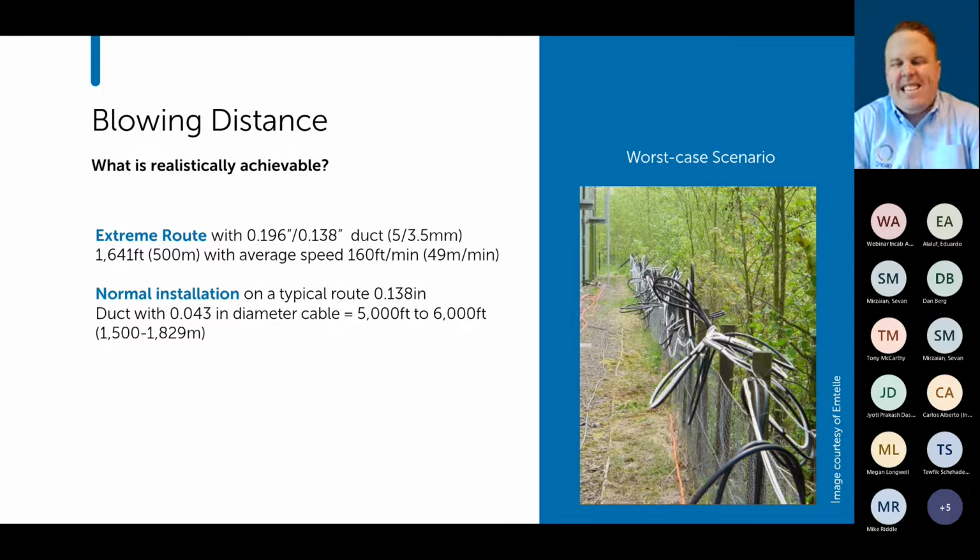We can see 5,000 to 6,000 feet out of a single run, which is, again, right, when we talk about a cost standpoint, if you can go 6,000 feet on a single run versus 1,500 to 3,000 when compared to a standard cable pulled through a duct, and your network calls for runs that long, all you're doing is decreasing the number of times that you have to install a handhole, a junction box, a splice enclosure, or splice point, whatever that might be. You're going to decrease that type of equipment.